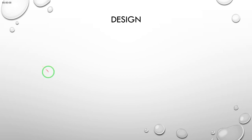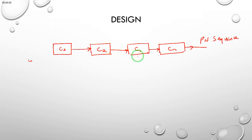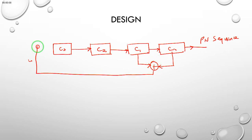So I want to give an example of a design that we are going to use. Consider this to be our S3. So this is C2, this is our flip-flop C1 or shift register C1, and finally we have shift register C0. In this model, the signal is flowing in this direction, and the output is obtained out of this. So this is where we are getting our PN sequence. The feedback is obtained as the linear combination or XOR of C0 and C1, and when we get this linear combination, we are feeding it back to our C3.